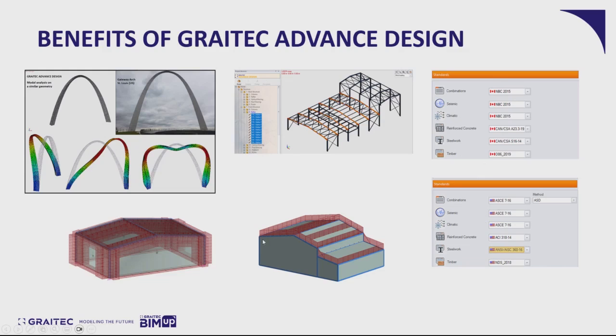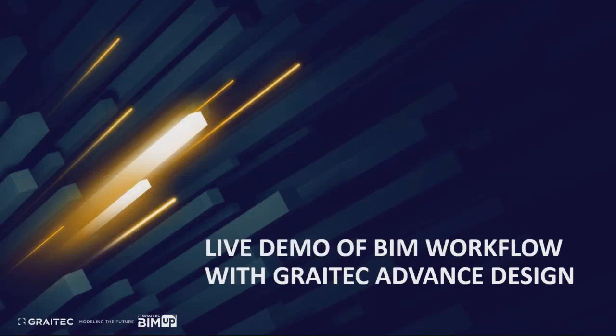And here at the bottom, I have two screenshots from the automatic snow load generator, and also the wind load generator on those structures. All of those loads will be generated automatically. You also have the option to manually check them to verify them. And in case you want to change the value or the quantity of that load in Advanced Design, you have the option to modify those. So it's a very flexible workflow and tools that we have in Advanced Design.